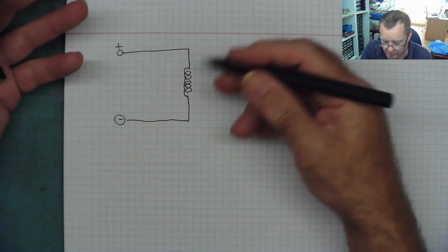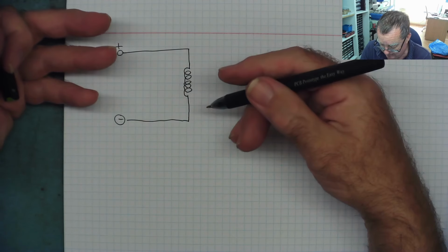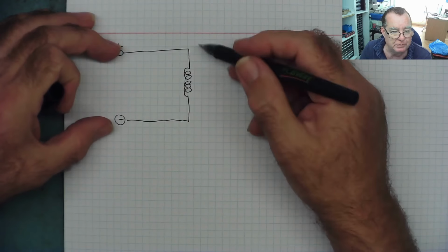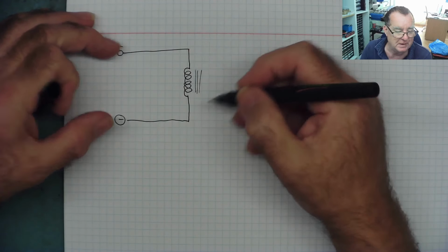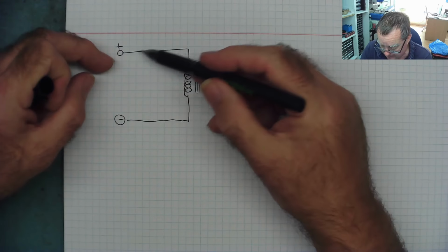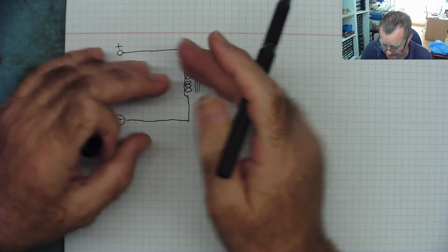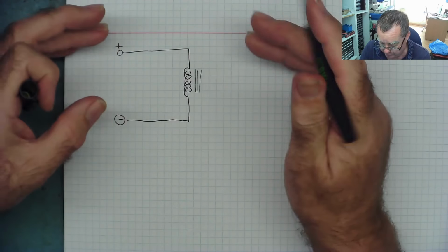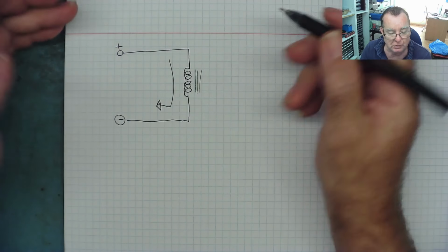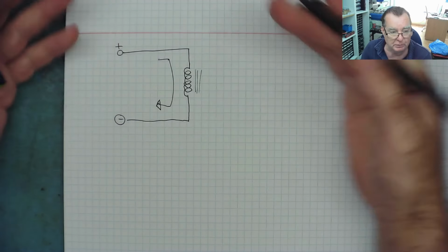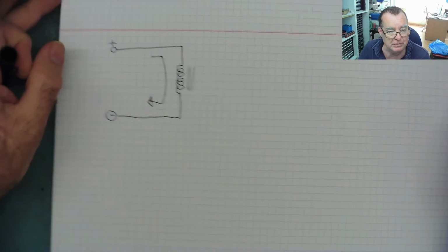And if you put your multimeter across it, that's what you will read. So when you apply the voltage to an inductor, for a fraction of a microsecond or however long it takes, the current will charge up the magnetic field in the inductor, and once it's fully magnetized, the current will pass straight through it and it will act like a short. And we can test that. We can use our multimeter and see how an inductor reads.